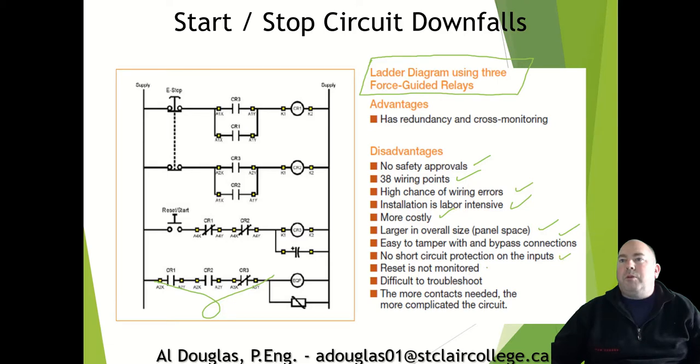There's no short circuit protection on the inputs. It says that reset is not monitored. That is true. You can actually jumper that out still. It's difficult to troubleshoot, and the more contacts needed, the more complicated the circuit. So there are some issues with this still. Okay, so functionally it's good, practically it might not be as good.